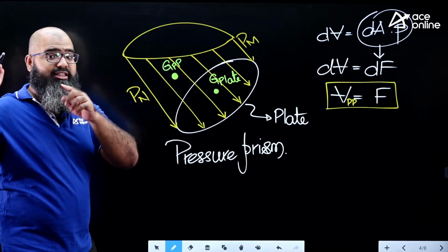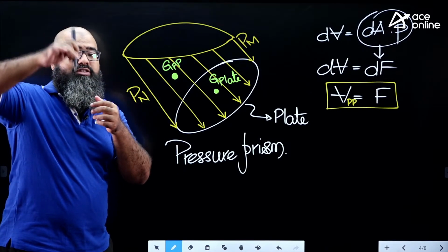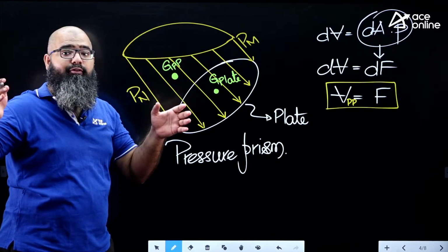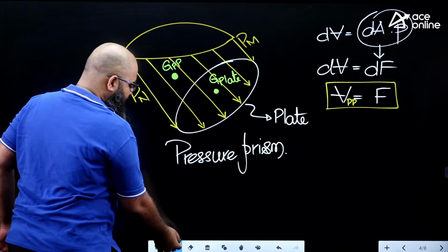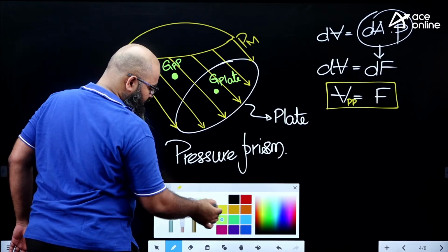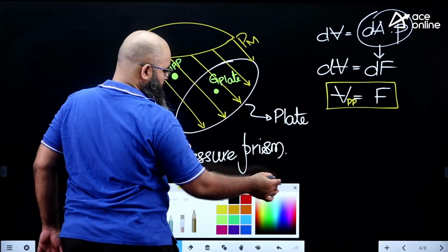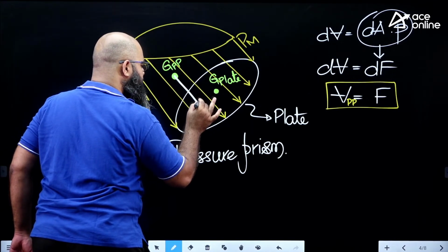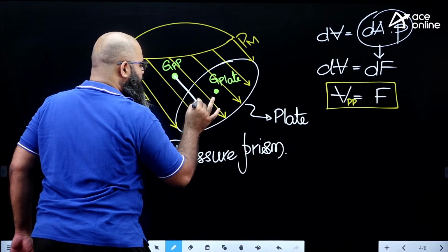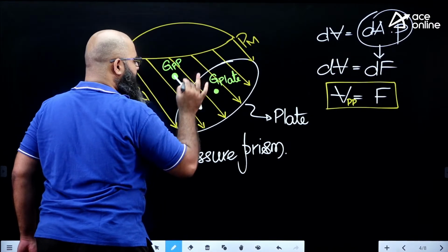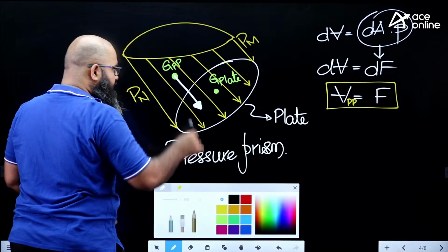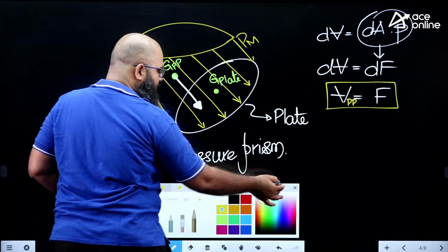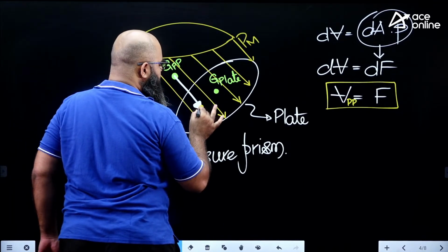Just like previously in the case of beams, you are saying the net force acting was through the centroid of the area formed. Likewise over here you are having net force passing through this particular point. If the net force, that is hydrostatic force, is passing through this particular point, then wherever this arrow is going to strike the plate, that particular point would become which point?